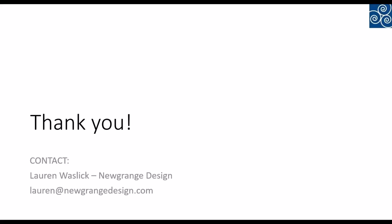That's a good question. I believe so, yes. You can have multiple nets selected and you can route them along that way. It's going to work. I don't think it's going to work on staggered layers like I had shown here, but you can choose the ones that are on particular layers and route those one at a time. So one layer at a time is kind of what I mean, not one signal. You can do a collection of nets on one layer. So yes, that should be possible.